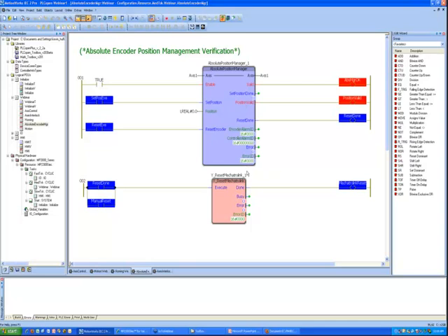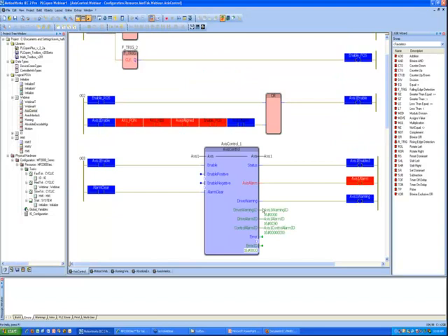Okay, so at this point we don't have an absolute encoder alarm yet, but I have unplugged the encoder and reconnected it. You'll see that if I switch over to the axis control function block, there is an axis alarm, and that alarm is AC9, which means encoder disconnection. This alarm is not clearable by a casual alarm clear, but requires a power cycle according to the documentation in the servo pack manual.